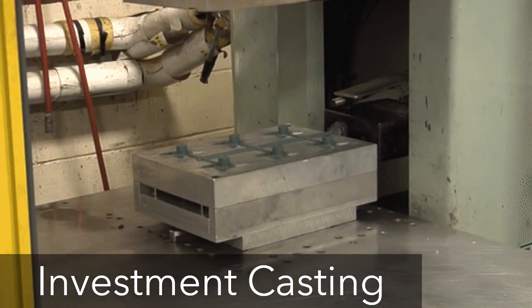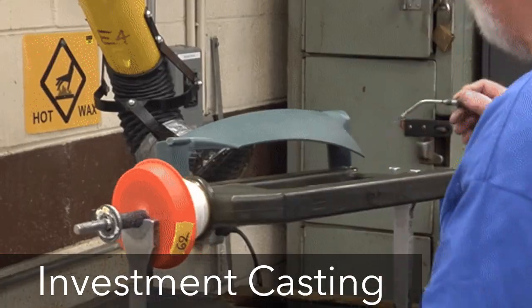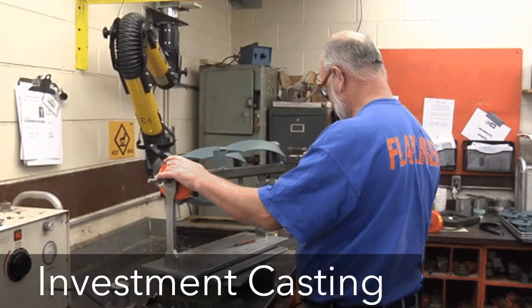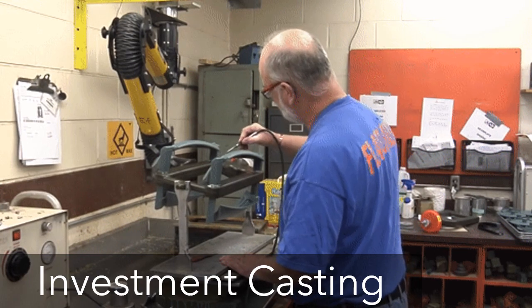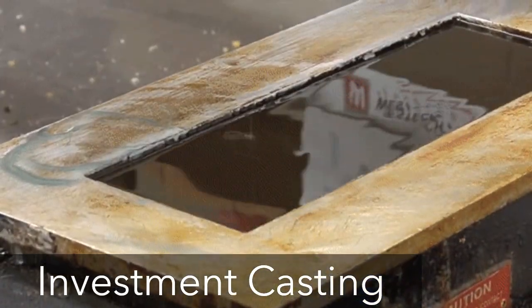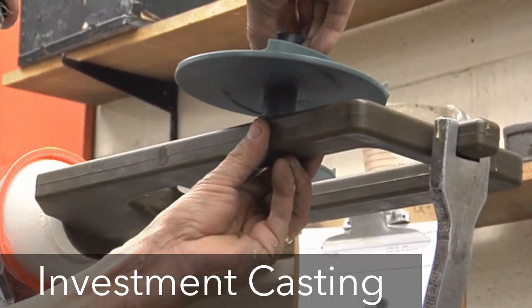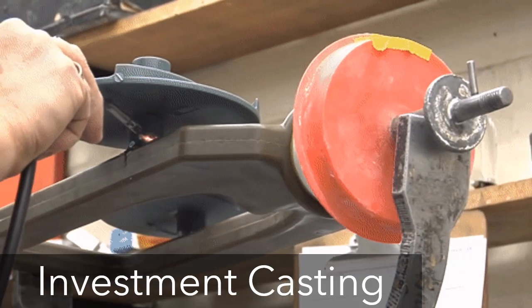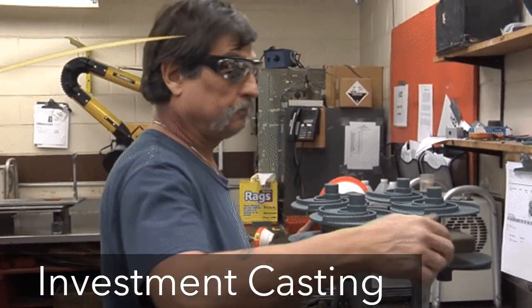Investment casting process, also called the lost wax process. The sequence involved in investment casting is easy. The pattern is made of wax or a plastic such as polystyrene, either by molding or rapid prototyping techniques. A number of the patterns can be joined together to make one mold, called a tree. A tree gives a significant increase in the production rate.